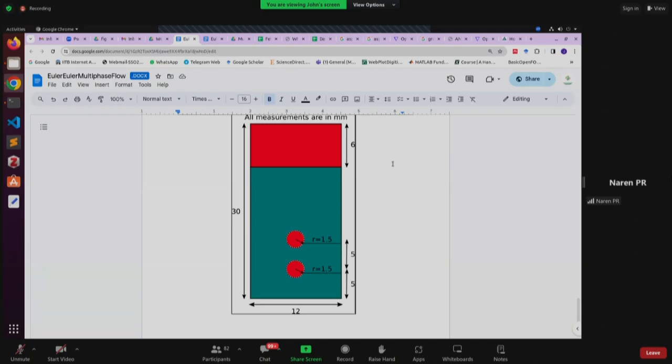In the mathematical equations, the drag force, lift force, Reynolds number, everywhere the linear dimension, the diameter, is an equivalent spherical diameter. So the model is developed assuming bubbles and particles are spherical in nature. I hope, Mr. Harsh, I have answered your question.